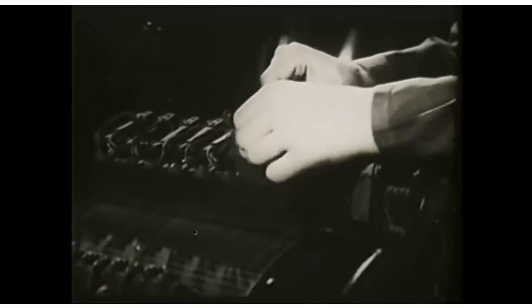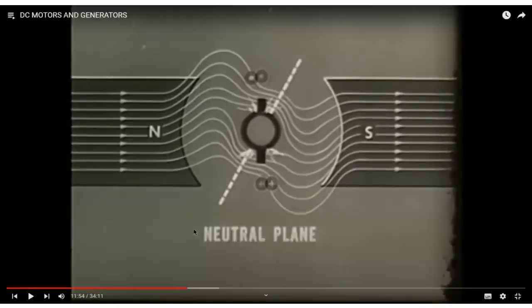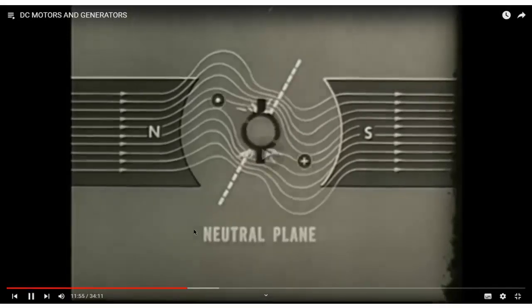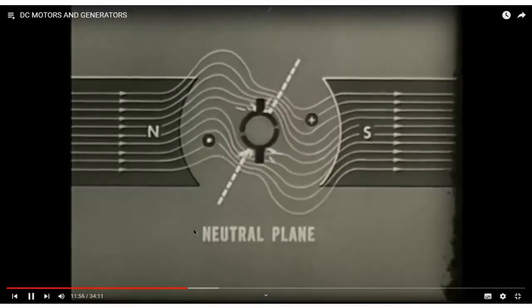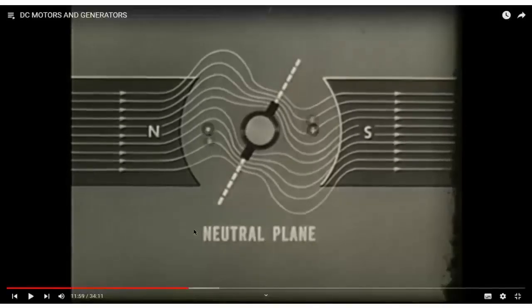Here you see the brushes. Take care. Brush position will be changed into the new magnetic neutral axis, adjusted to lie in the adjusted neutral plane. Aha. There's no sparking right now. As you see, you have adjusted brush position.